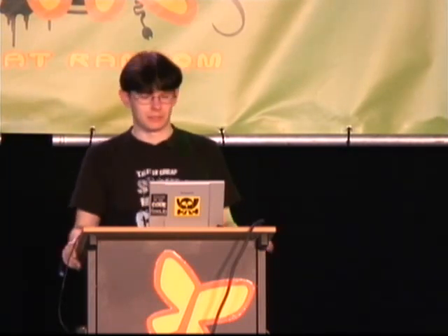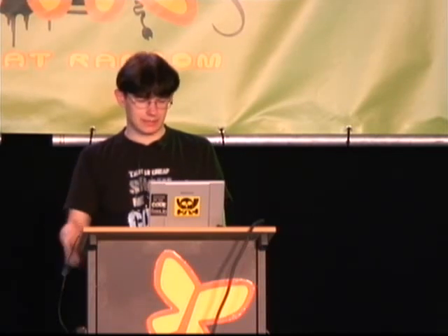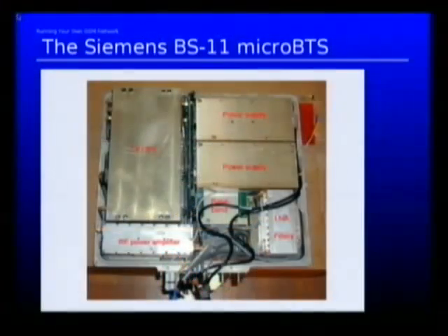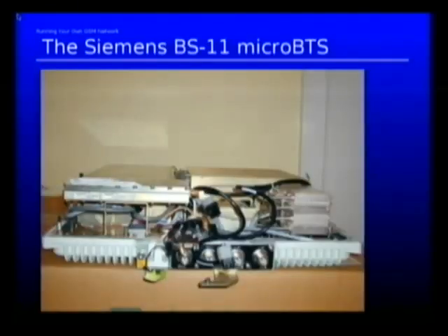And we have a free software implementation called BS11 config, which basically does what the LMT would do, but it's not proprietary. I have a picture of a closed one as well. If you open one of these BTSs, you will see multiple units in there: an RF power amplifier, LNA, baseband, power supply, transceivers, and so on. You don't actually have to open them, obviously, but we did open them, so I thought I'd show you some interesting pictures. This is the stacking from the side.